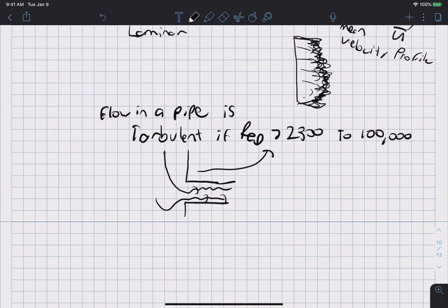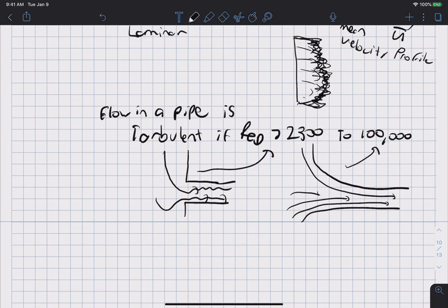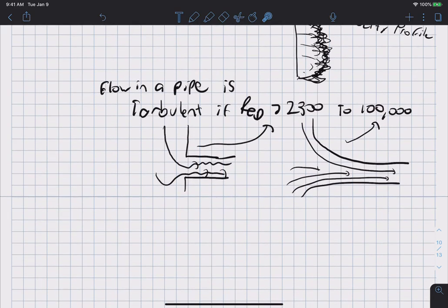And in another experiment, he did it up to a Reynolds number of 100,000, and he very carefully contoured the flow, and then the streamlines just nicely hugged the contours, and so it took a lot more for the nice laminar flow to devolve into a chaotic turbulent flow. Okay, and there are specific fluid mechanical reasons for why this case with sharp edges and things like that is more prone to turbulence.